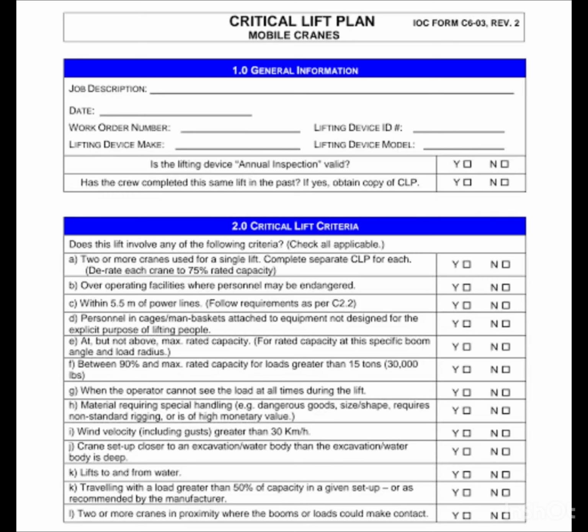Hazardous conditions like near power lines, confined spaces or over operational facilities, or while lifting sensitive or valuable loads. Lifts with potential for significant consequences. Non-routine lifts, all loads above 40 tons or more.